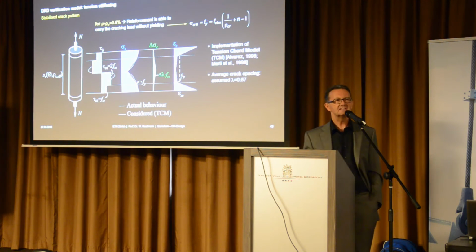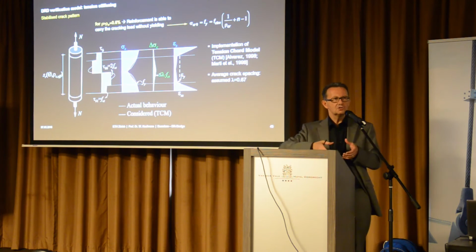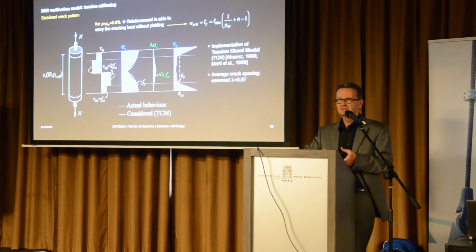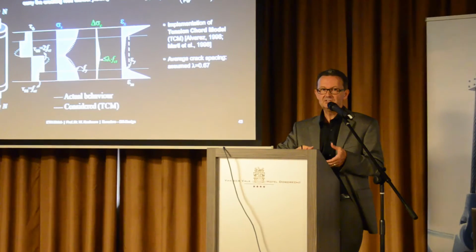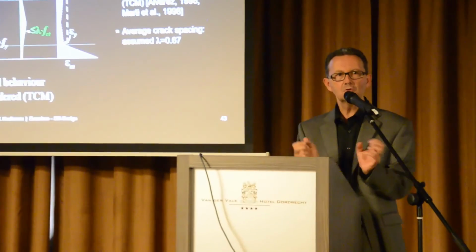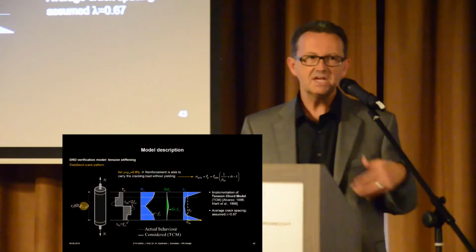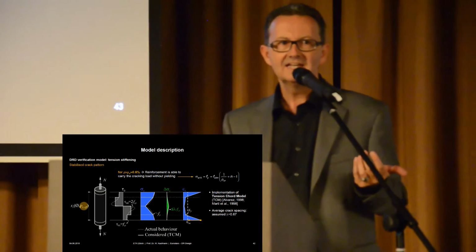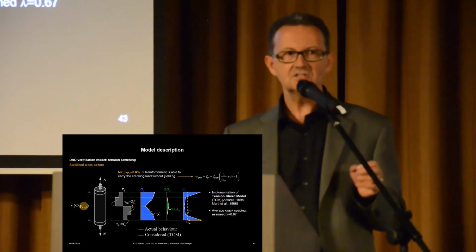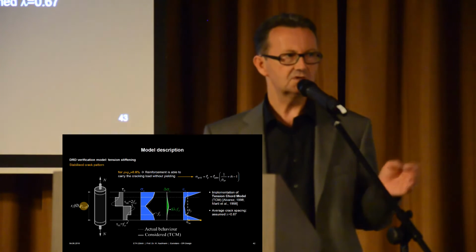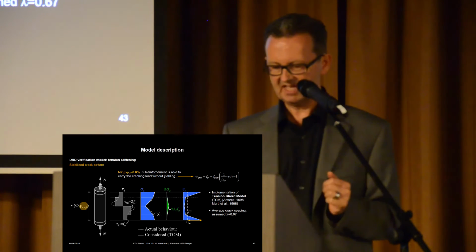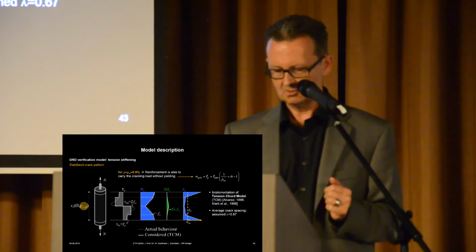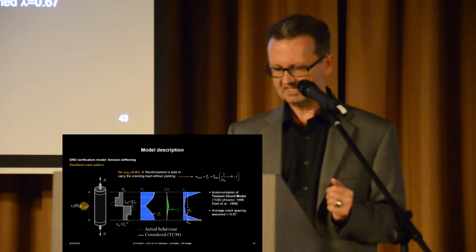You have to be aware that this bond stress, a constant bond stress along a nominal perimeter of a rebar, is a very drastic simplification by itself. It works completely different. The ribs are transferring the forces by local compression and so on. Many people have investigated that. And then the question is, should we really, if we're in the end of the day interested in the integral behavior of average strain versus force, do we really have to care about if this curve looks like this or if it looks like this?